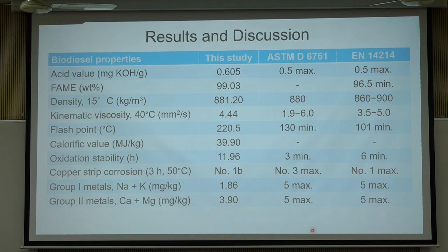Is there any tolerance on the benchmarks? Okay, that one is based on the final biodiesel that we are using. For example, you see, this one is based on 100%, B100, I mean 100% biodiesel. If you mix maybe 80% diesel with 20% biodiesel, the overall acid value might be 0.4 or whatever. That's the thing. It means we cannot use 100% pure biodiesel. It cannot be used like that in the system. There is no tolerance.